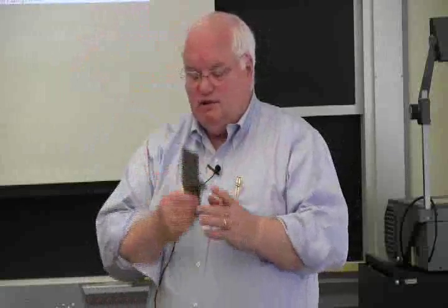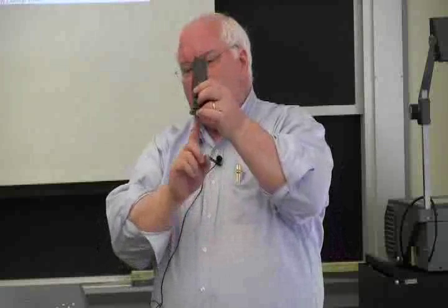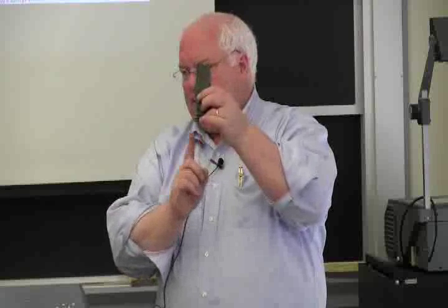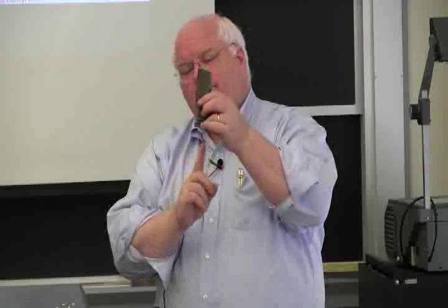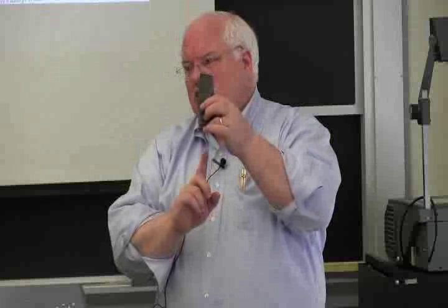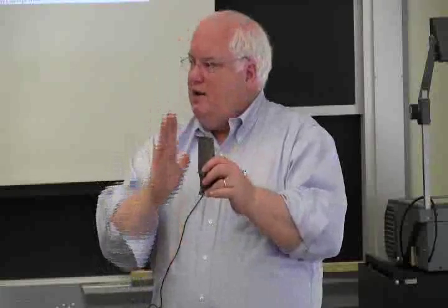If you want, and this one actually is the $6,000 blades, are single crystals. They start out with a little wax pigtail on the original casting. The pigtail is a corkscrew spiral. And what happens is when you slowly start solidifying that, you start with a seed crystal that has a particular crystallographic orientation, because these things are going to be at high temperatures and they have a greater high temperature strength with a particular crystallographic orientation.